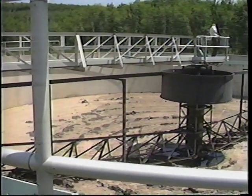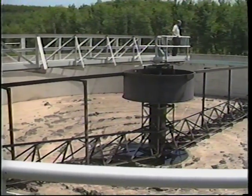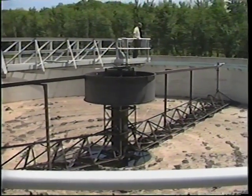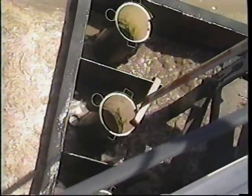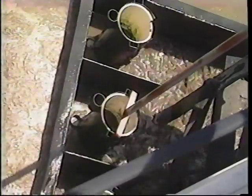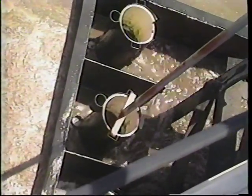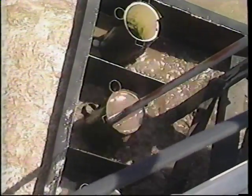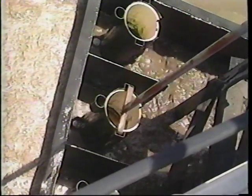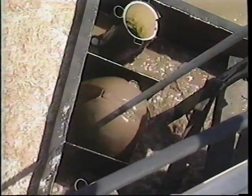Some circular clarifiers that are designed for settling activated sludge may have pipes that sort of vacuum the activated sludge from the bottom of the clarifier. This type of clarifier unit can operate with pumps either hydrostatically or off of differential head. In either case, removal of the biosolids in this fashion is necessary because the activated sludge tends to be light and does not compact as well as primary sludges and is therefore difficult to move effectively with scrapers.